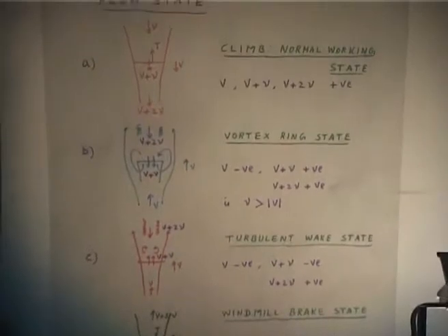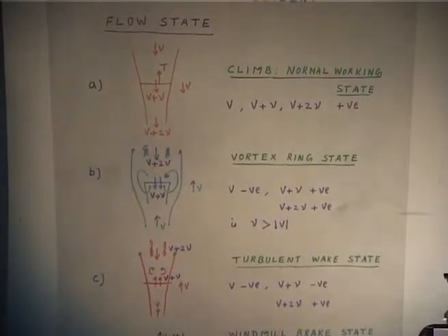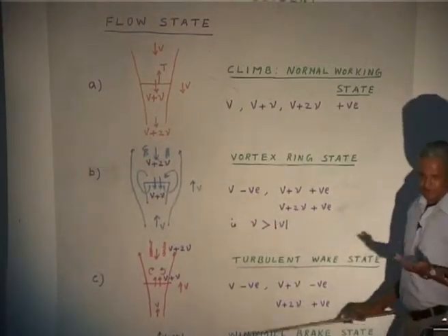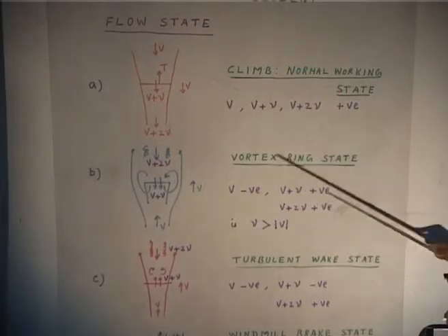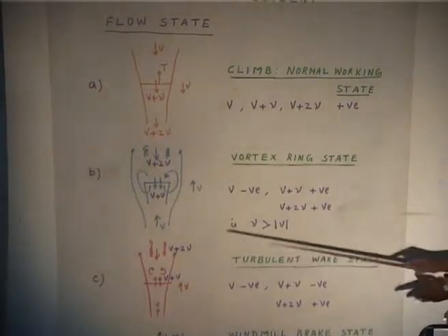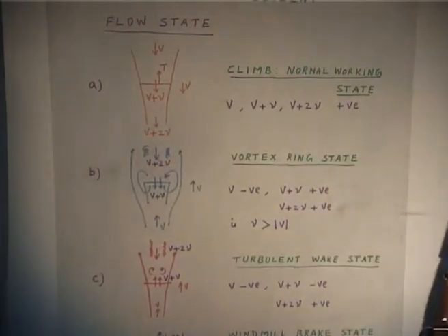is still, if you say, small, because you have an inflow. If you are hovering, you will get a value of inflow in hover. You started descending and your descent velocity is less than the inflow. That means inflow is large, this is less, though I put the symbol V plus nu because V is actually opposite, nu is down, this is up, but nu is large. So, V plus nu is more, I have put this direction down, please understand, I have put the direction down.